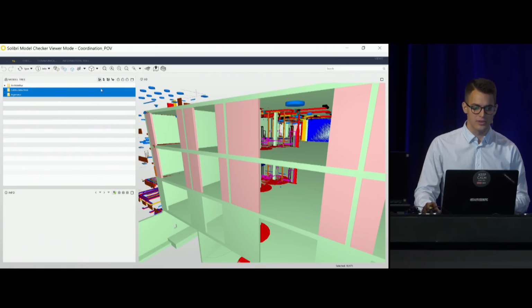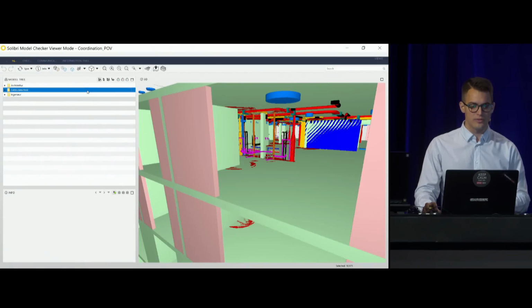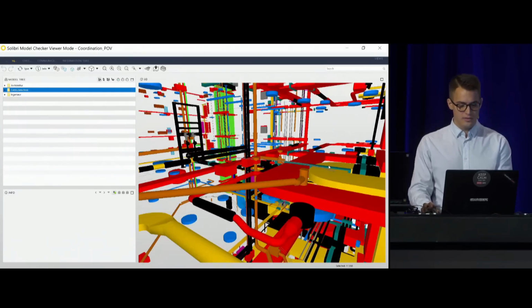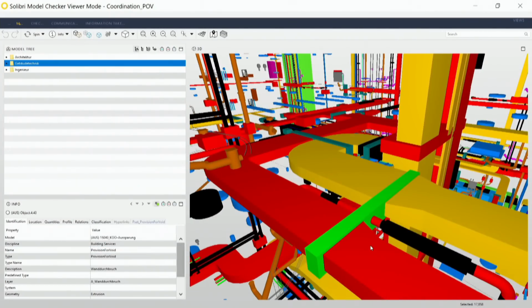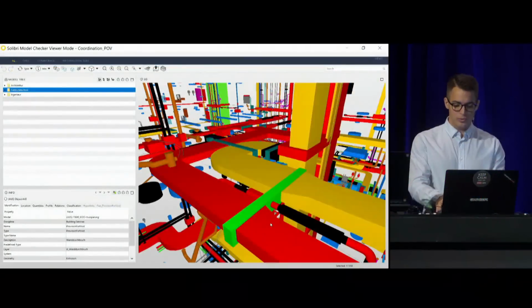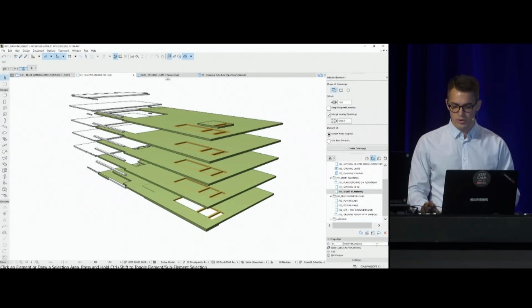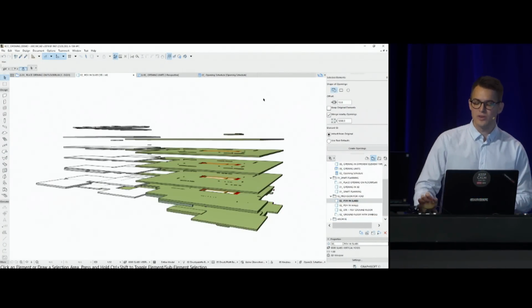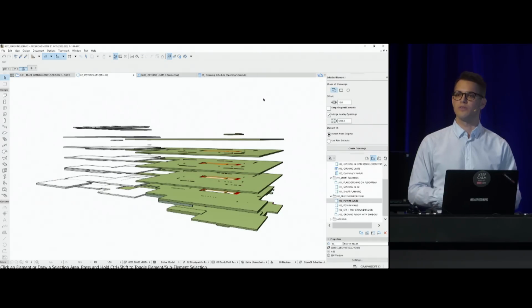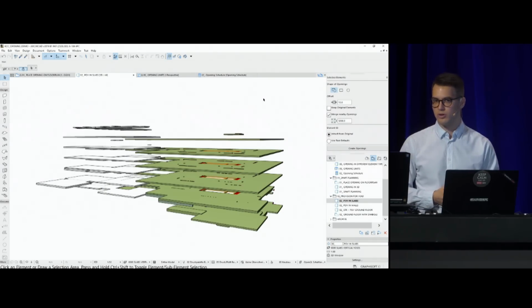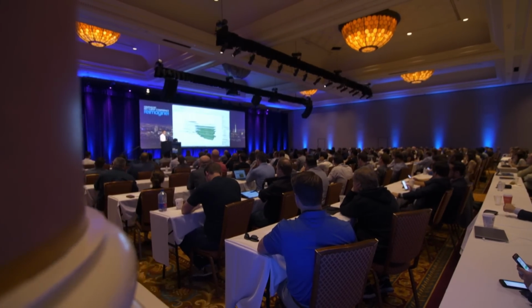How could I locate these elements and where they are? They highlight these points by sending us provision for void geometries. And with the help of these editing bodies, we can create our openings in our own file based on the MEP model. So, switching back to ARCHICAD, I'm just going to switch one view. So how do we receive these files? These provision for void geometries will be part of the imported or hot-linked MEP IFC model, but not part of the MEP structure. They will be an editing aid for us, which we can use to create the openings.